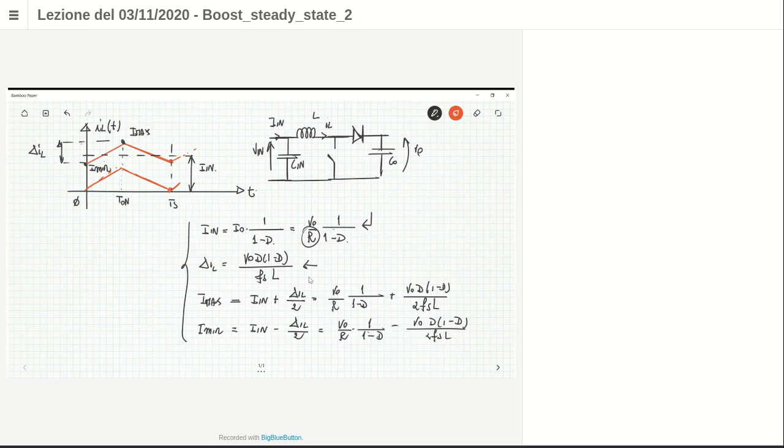It means that you are in the discontinuous conduction mode. In that situation, since the inductor current goes negative, the diode and the switch can be off for a certain interval of time during the period Ts. So that is the discontinuous mode. So the critical boundary divides the CCM and the DCM operating modes for the converter. In all the situations we analyze, the boundary condition is defined at the point at which the minimum current is zero. Critical or boundary.